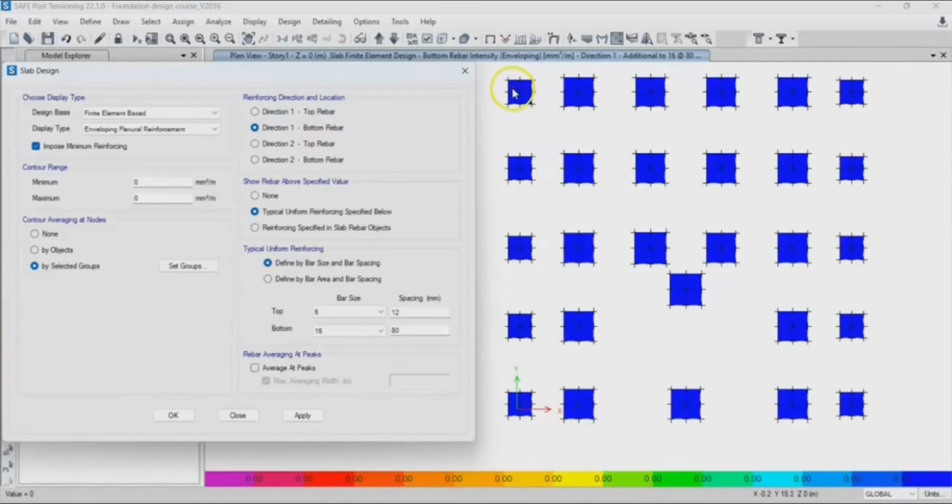Then providing isolated footing is just going to be a waste of money, and it is going to be very difficult to excavate the footing on site. So in that case, why not just provide mat foundation? Okay, so this is a general rule. Most structural engineers go with this rule. So if the total area of your individual footing is less than 50% of your total building area, then it is fine. You can go with isolated footing.